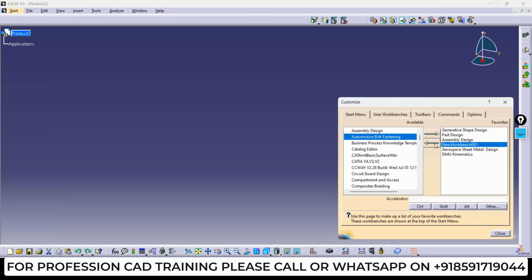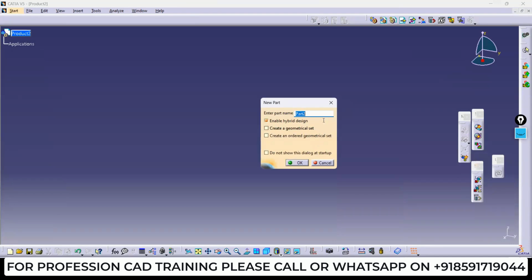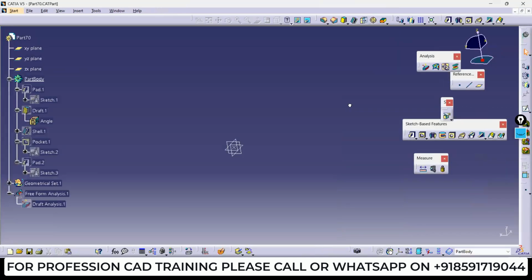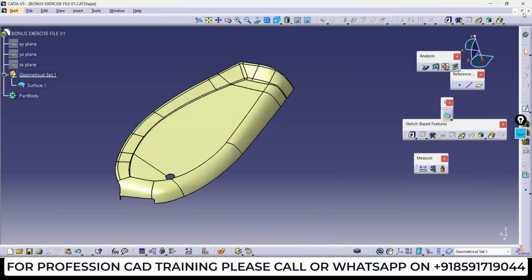Then the new workbench, if you don't want it, remove it. Whatever you are using frequently, you can add here. You can close it, add or remove. From this, everything is available, you can add and you can remove it. So this is the start menu setting you can do in your CATIA. So now, this is the basic understanding required to understand the CATIA user UI.